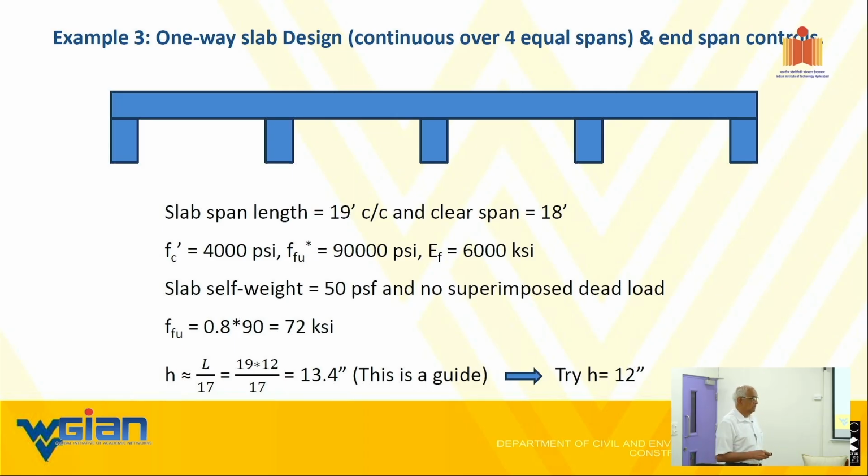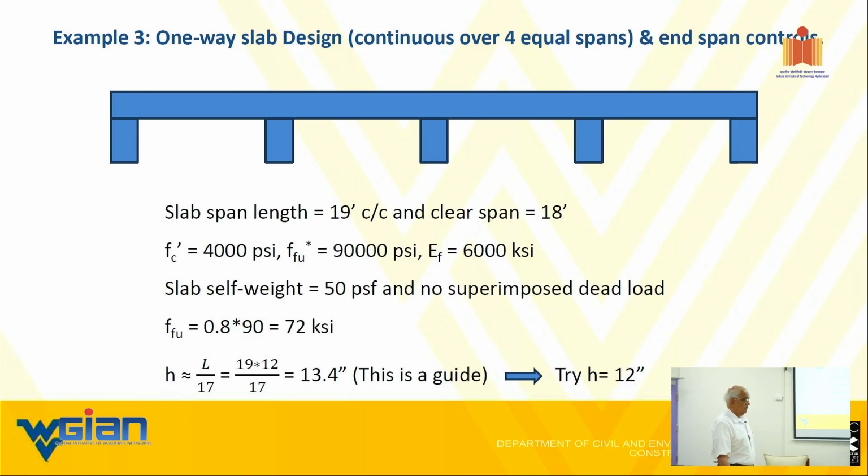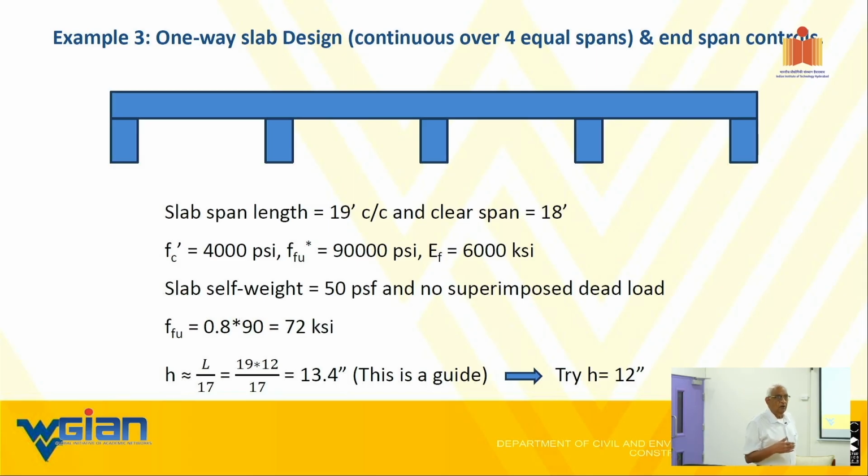Quick question. Typically, the L by D ratios that we use for steel are on the higher side. Probably because this is governed by... Exactly. That is the key point. The L by D ratios for steel are going to be higher than for FRP. That's because of deflection.